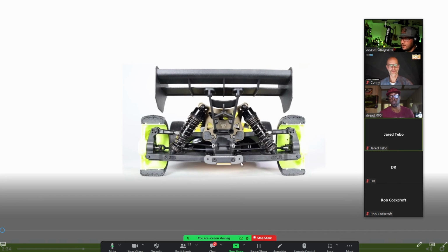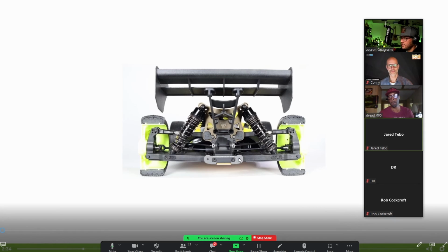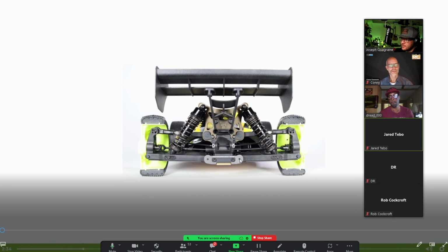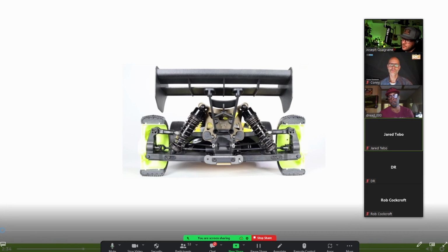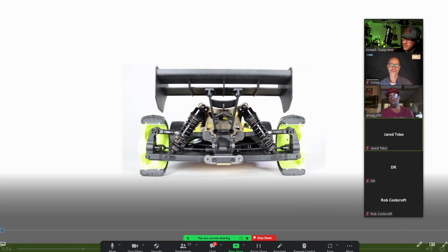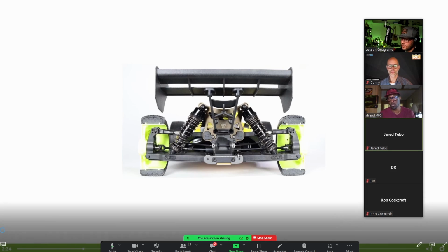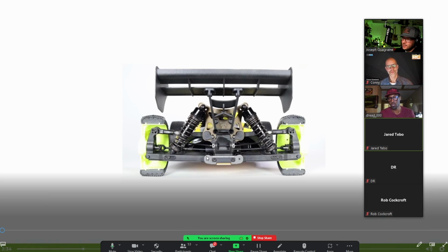that point. But when I adjust this, I don't adjust it for traction, really. I don't really think about grip when I'm doing this. I'm thinking about support, because this affects rear end support so much. So if you lower this point, you have less rear end support. So as you accelerate, the rear will squat more onto the outside tire as you're exiting a corner. If you raise this position, the rear will stay more flat and it won't squat as much. So when I adjust this, that's what I'm doing.